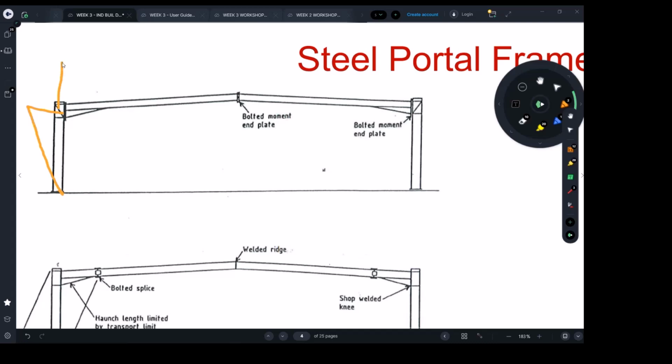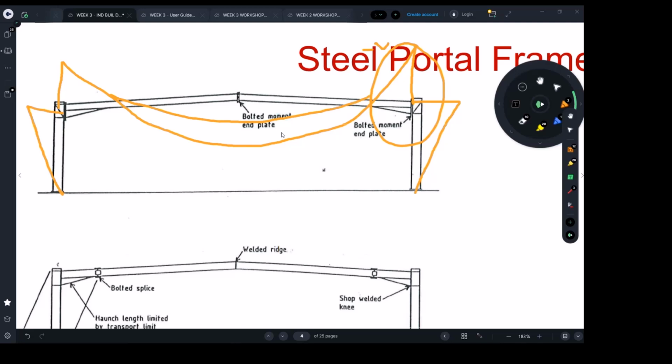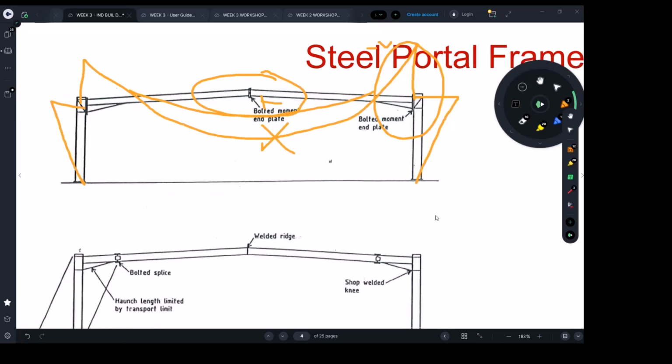Then the bending diagram will go like this. Then it can curve and go to negative again, and it's going to look like that. This is the bending moment diagram. So why would someone ask why we're using a haunch here? Because here we have negative bending, and usually the value of the bending here is very high. Maybe my drafting is not right, this should be less. This is too much positive bending. Usually the positive bending here is less than at the ends, and that's why at the ends we need more.